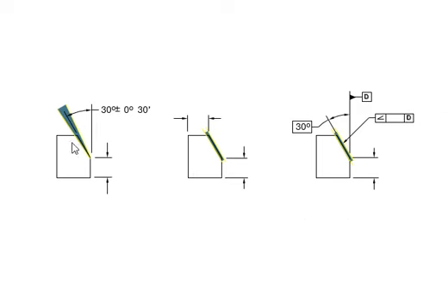Exaggerated, your angle, parallel tolerance zone right here. And here's your datum plane right here, and we know that this angle, we want it to be 30, and we know the tolerance, plus or minus right here, given to you for that zone. Then we're going to put the leader, and then your control, because it's showing you this tolerance is going to control that angle right there.